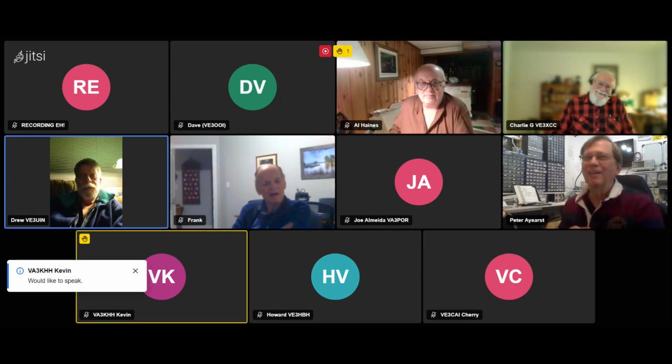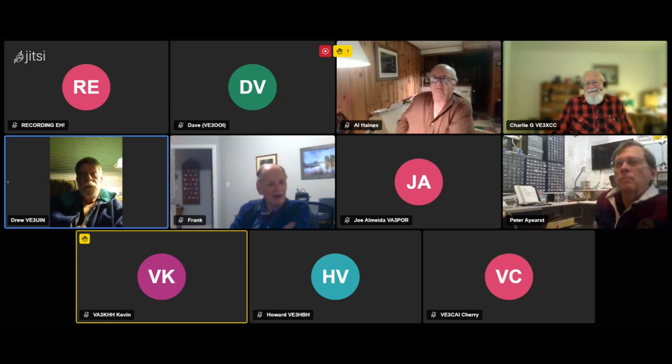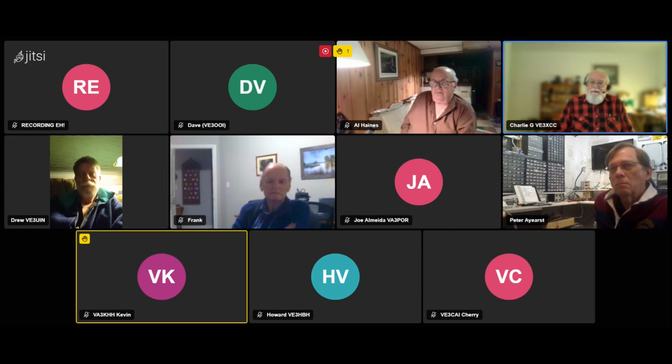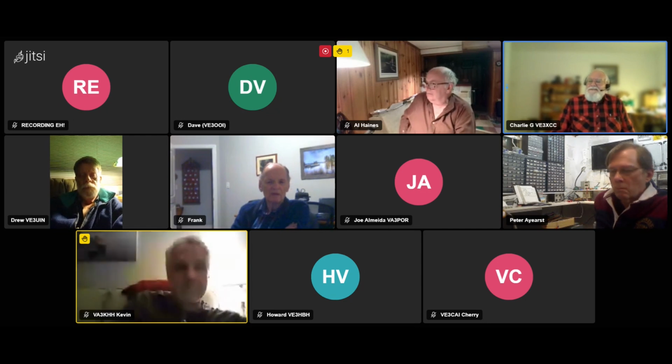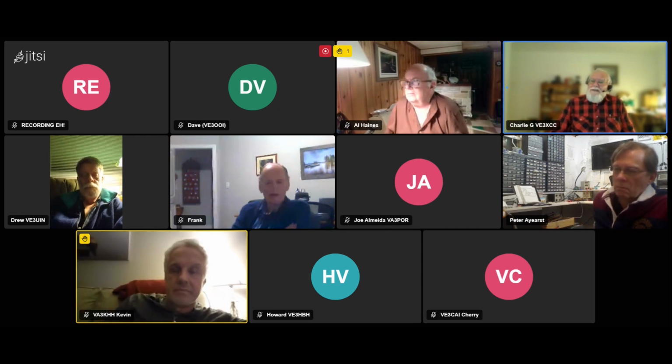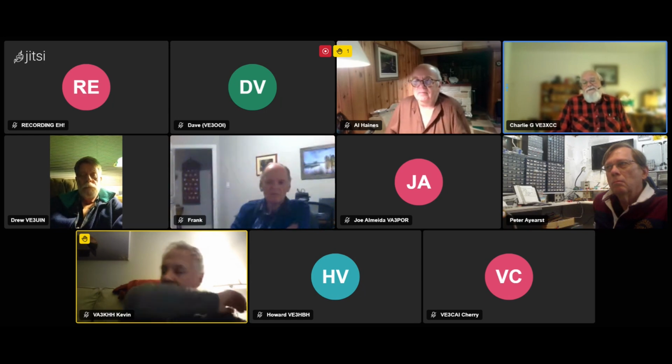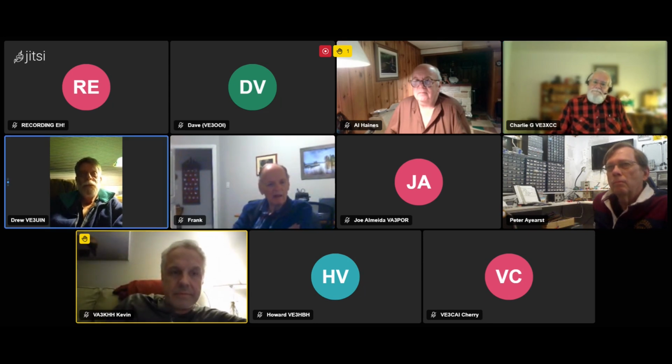Well, just before, I don't want to dominate here. On the UHF VHF side, you were using a clamp-on ferrite. Yes. Okay, so it's just the plastic like you would put on a monitor. Yeah. I found a bunch of them of different physical sizes: 3 millimeter, 5 millimeter, 7 millimeter. Depending on whatever cable I'm using, I would put a few of those on. At UHF, they're great, and even at VHF, they're not bad. But at HF, they're pretty much useless. Well, I have UHF, VHF, and I have noise, so that will help. I do have those. I'd never tried it. Thank you.